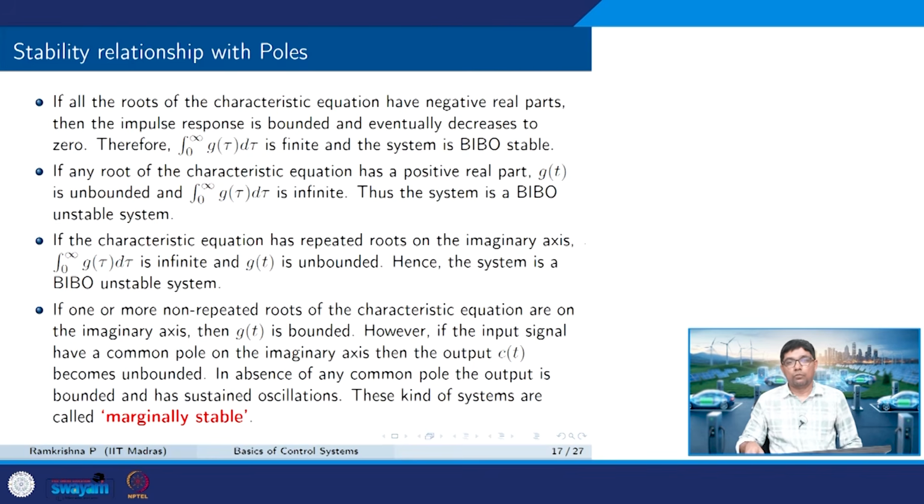Okay. Now, the conclusion here is that I can represent the system as a transfer function, and from that transfer function I can infer stability of the system, right. And then what was stability? Bounded inputs should result in bounded outputs. System will result in bounded outputs only if the impulse response is absolutely integrable.